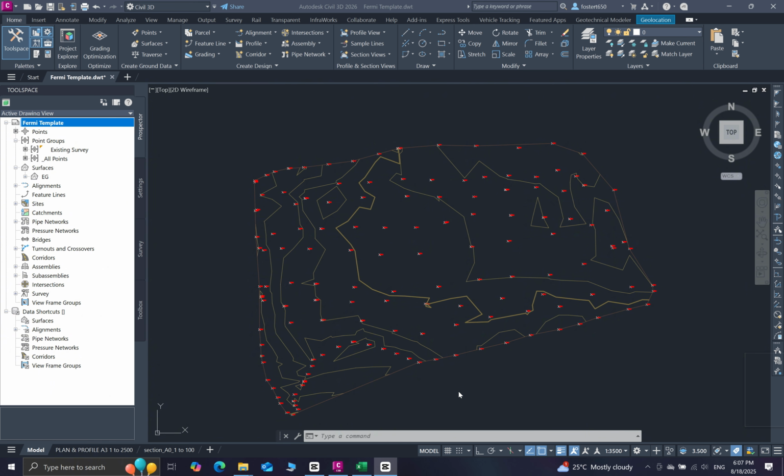Now, with the alignment, they don't necessarily have to pass through the center line of our road, in case we went through a site to pick the data and it's a road. The alignment that you create in Civil 3D doesn't necessarily have to pass through the center line of the road. It can pass through anywhere, so far as that section is your proposed roadway. But then alignment is what we use to build our roadways or railway lines inside the Civil 3D designs that we make.